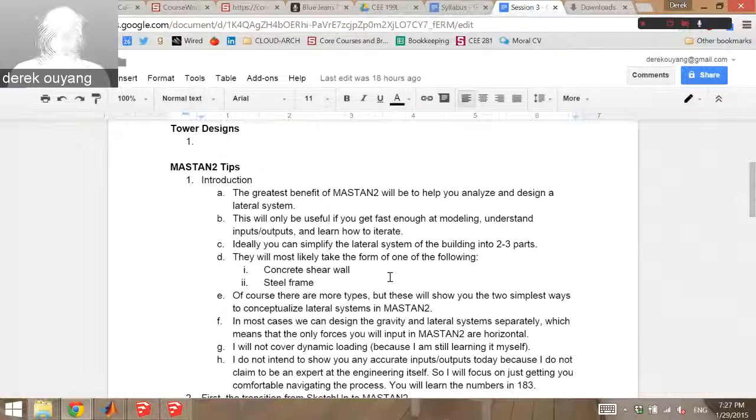And wind loads, as you can see, vary with height. It's really just a PSF against a face of your building, and then a negative pressure as well. So that's what you're really going to focus on for horizontal loads. And you can almost think of most of these, of course I'm generalizing a lot here, big towers as a gravity system working pretty independently from your lateral system, which means that you can just expect every floor plate to work fine with the columns you design for, and that's not even thinking about wind loads yet.